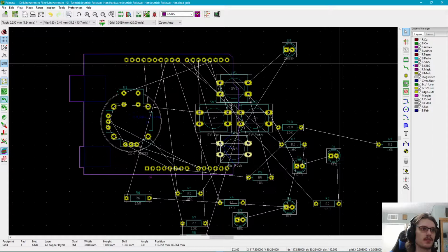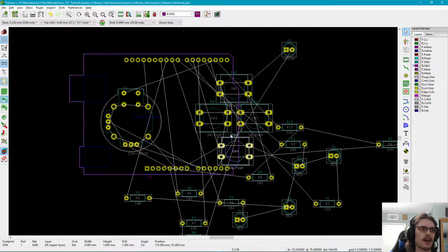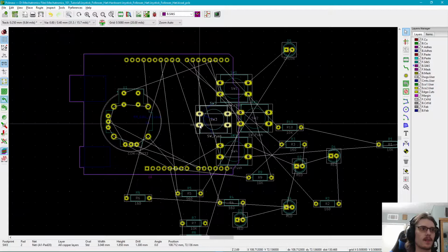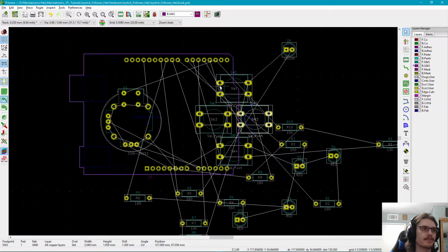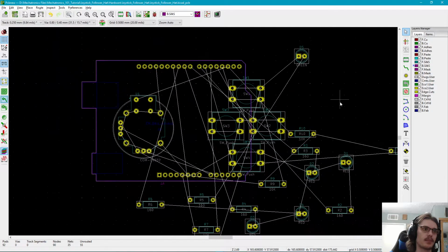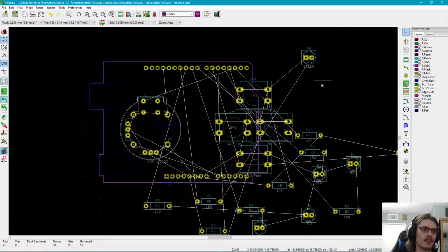And then we'll put the fourth one down here. We'll give it some space so the actual silkscreen text can be visible. So let's move this one down too. This one down. Yep. Move this one up. Okay, so the turquoise we want visible. Anything else can kind of overlap, unless it's a trace.